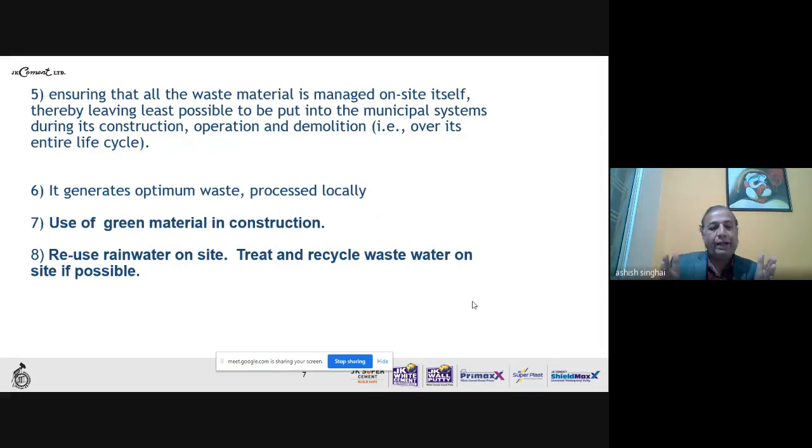So Bureau of Indian Standards has given provision that instead of OPC, if we switch to Portland Pozzolana Cement or Portland Slag Cement, in that way not only are we ensuring that waste material from thermal power plants, that is fly ash, and waste material from steel plants, that is slag, is being used in very good quantity, and still, after mixing it with cement, we get a very good quality product that is not only long lasting and durable, but at the same time qualifying as a green building material.